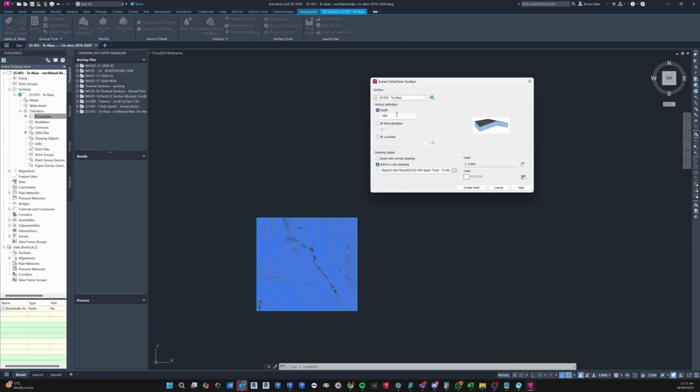So it will create something 100 meters deep because we want to see only one line on the top. So when we cut a section on Revit, we don't want to see something 1 meter below the other surface. So 100, we will never see something 100 below. Or maybe we do, but we will do it like this. And then we will create the solid.